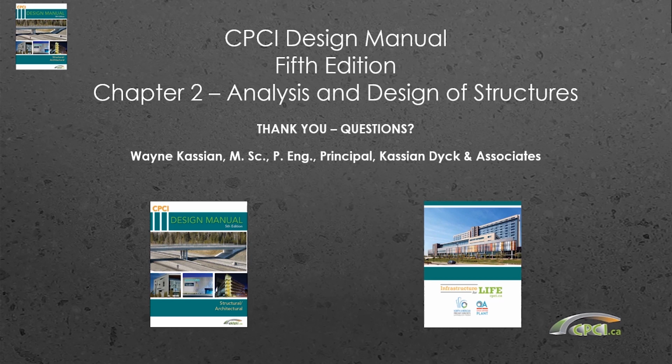Are ductile shear walls with precast concrete wall panels practical to construct and design in high seismic regions? Basically, with ductility, you design for lower forces. So the higher your Rd and Ro factors, the more rebar detailing you put into your concrete elements, to allow that energy to be dissipated and to undergo deformations without breaking, so it's very ductile in an earthquake.